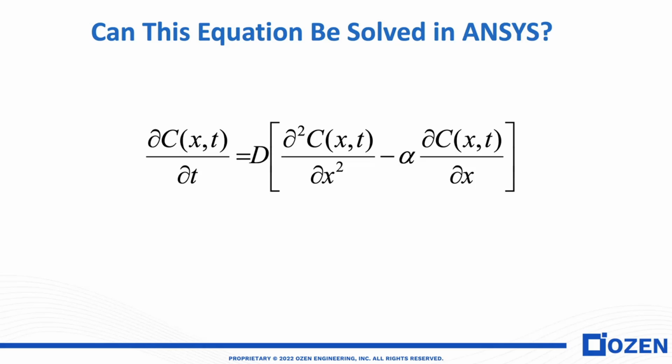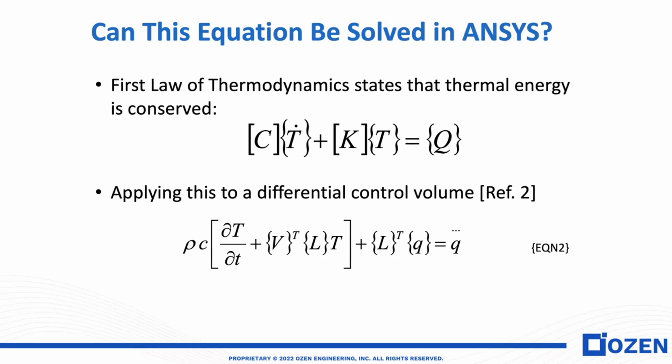So in the traditional electromigration equation, again listing it here, the question is, can this equation be solved in Ansys? And when I say Ansys, I'm talking about Ansys Mechanical at this point in time. Can we solve this equation in Ansys Mechanical? And the answer is yes. And here I'd like to explain how you can make use of Ansys to solve this traditional electromigration equation.